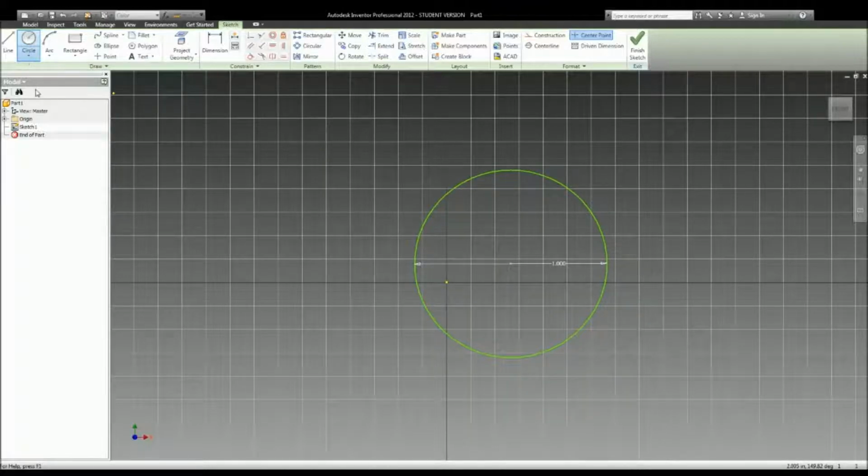But if I wanted to do a circle tangent, it's actually really interesting because you can't just draw it normally. You need tangents to draw the circle. So I'm going to go ahead and draw a line here, a line here, and a line there. Okay. Now I'm going to do the circle by tangent. I'm going to go ahead and click these lines. And voila, I have a circle that is fit within the parameters of these tangents.